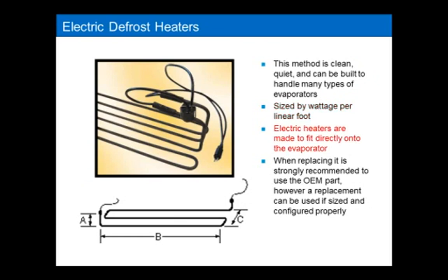So you want to make sure that you get the right fit. You just don't want to use any heater that just lays on the coil. You want to get the heater that fits into the coil properly. So in general, it is best to use the OEM. Now there are companies out there that make